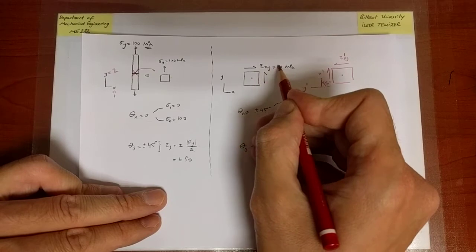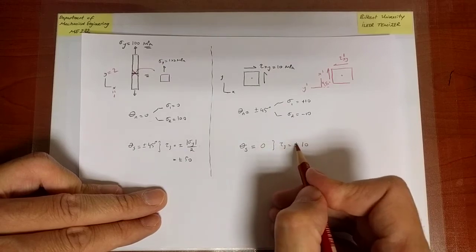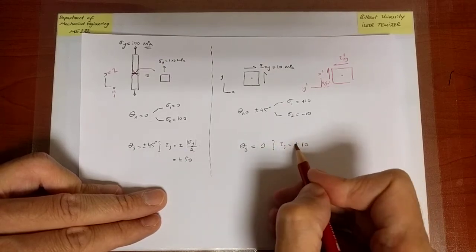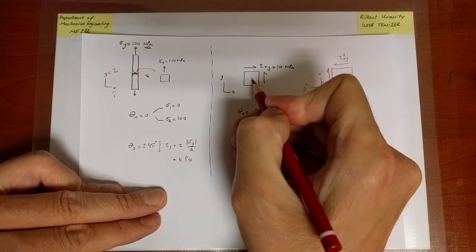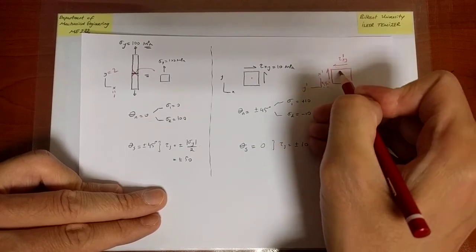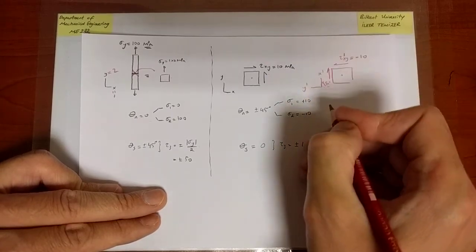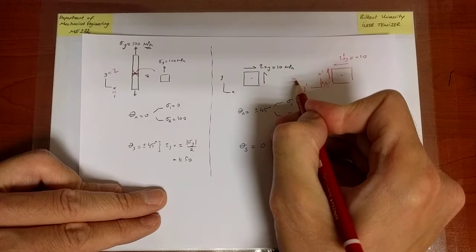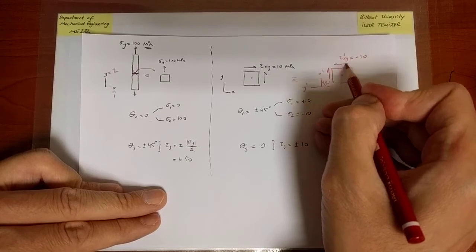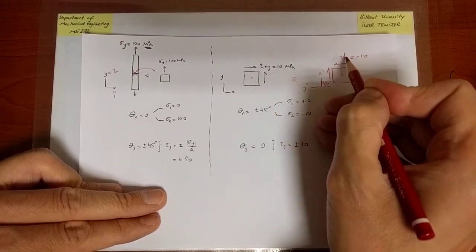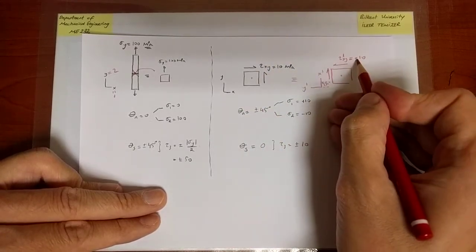So here, tau xy is plus, okay? So in other words, there is already a principal shear stress, okay? That is plus minus, right? That is equal to plus 10 MPa. But if I rotate through 90 degrees, then I get a shear stress, which is supposed to be equal to that picture. And therefore, on that picture, tau xy prime is supposed to be equal to minus 10 MPa. Why? Because the two pictures are entirely equivalent, also in terms of orientation. And for this to be equal to that, for this given default choice of direction, which aligns with these axes, the value must be negative, so that actually it is in the other direction, just like here. So that's where the minus comes from.